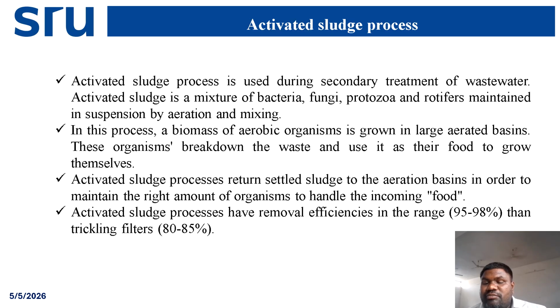Then the organic matter present in the water gets eaten by the microorganisms, and the microorganism population will grow. Next to the aeration tank there will be a secondary clarifier. Here we need to provide some residence time, so that whatever sludge is there gets settled at the bottom of the tank.